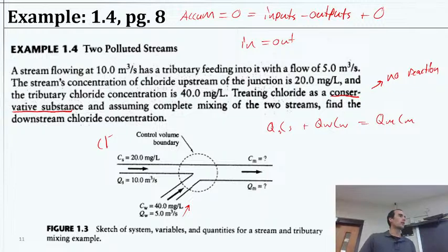So just a quick note here. We'll pick up here next time, but as you approach this from this formal mass balance of thinking, what you would do is notice that you can solve this mass balance equation to become inputs equals outputs, and then you know your inputs, so that would be the Q times the C plus Q times the C for the waste equals the Q times the C for the mix. So we can resume there next time, and have a good weekend.